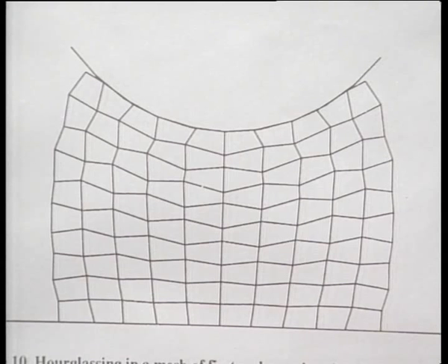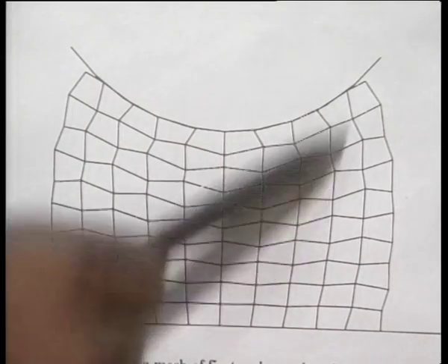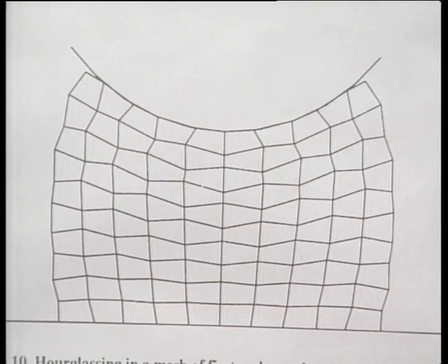What is that you see in that mesh? The mesh is very jagged. This problem has been done using what we call reduced integration, and what you get here, this jagged mesh, is what is called Hourglassing.